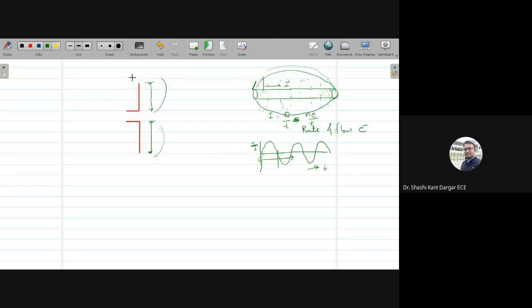So we will take this length of a wire first. L is equal to 150 millimeter. We'll divide this, and in between, the gap for the feed lines, we'll take as 20 millimeter. Another one is the diameter of this wire, which we'll take as 5 millimeter. This diameter is D. With this, let me start the practical now.